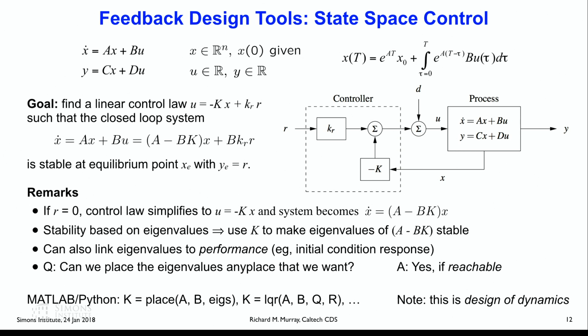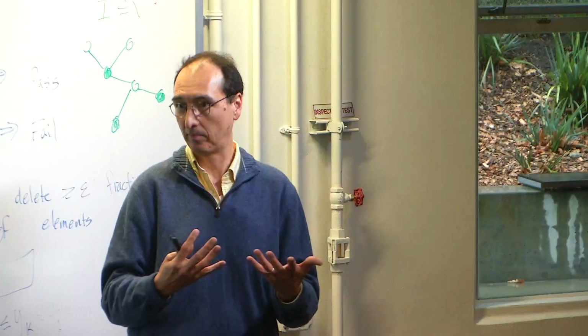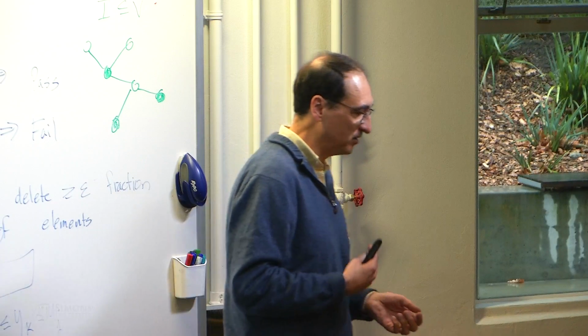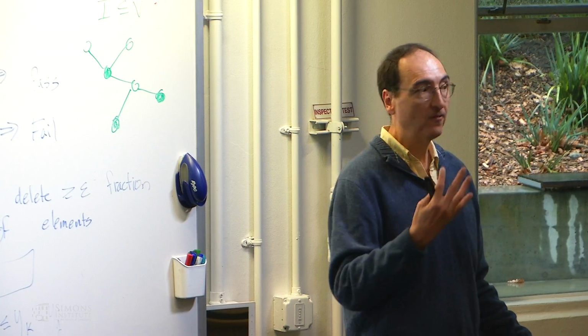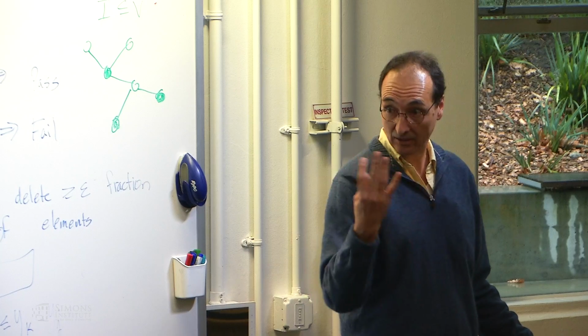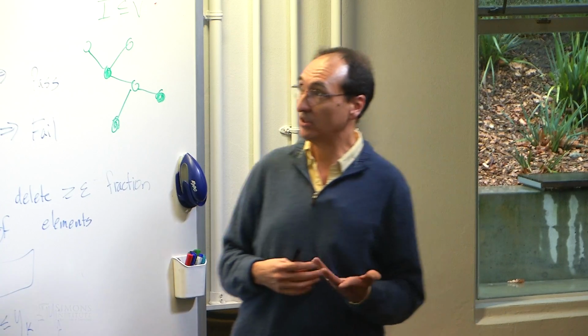Okay, so for feedback, those are the two primary techniques that we use to start with: PID control, with the integral being very important, or state feedback, often using linear quadratic regulator theory, sometimes using what is called pole placement or eigenvalue placement. As I mentioned, the student came to me, and that's only part of the problem, and increasingly that's the simple part of the problem that you've got to do right, but it's not the part that gives you really good performance. The part that gives you really good performance is the feed forward part, the planning part, that front end. So how do we solve that problem?